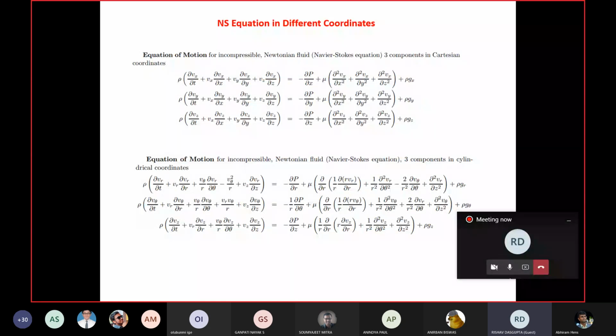We will take a simple partial differential equation first, maybe a heat transfer equation, and try to solve it following the finite difference or finite volume method. For example, a one-dimensional unsteady heat conduction problem, which is a simple second order differential equation. If we can solve that problem, that methodology can be adopted for these big equations also. That we will see later. But let us first understand with the help of a single equation.